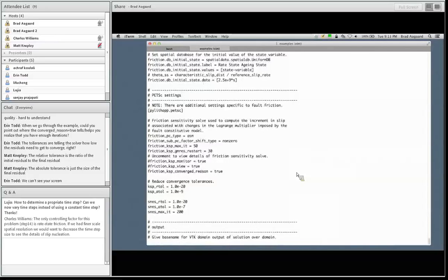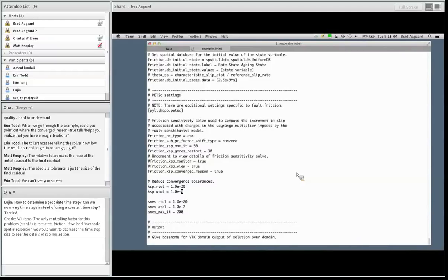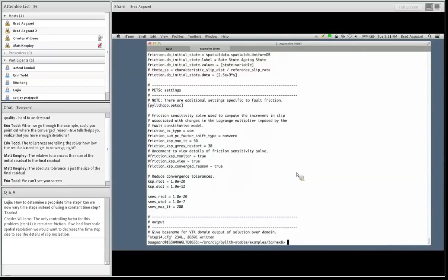And so you notice what I did is, here's my absolute tolerance. Well, my absolute tolerance from a linear solver is 10 to the minus 9. So it's bigger than my friction tolerance. So I better push it down to, let's say, back to 10 to the minus 12. So that's absolute tolerance 10 to the minus 7. Let's see what happens if I keep it at a pretty big value.